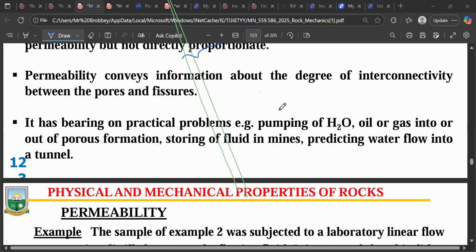If it's very permeable, it makes the water move freely and come onto the surface of the floor, which sometimes affects operations if a proper drainage system is not done to channel it to a sump or something. Oh, okay. Yeah, thank you very much.